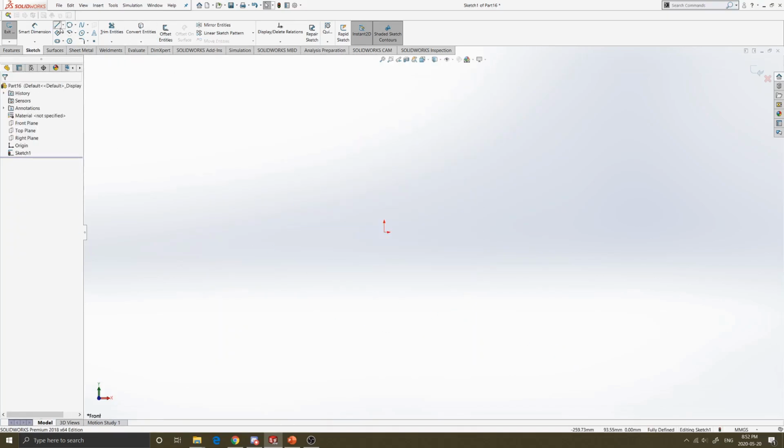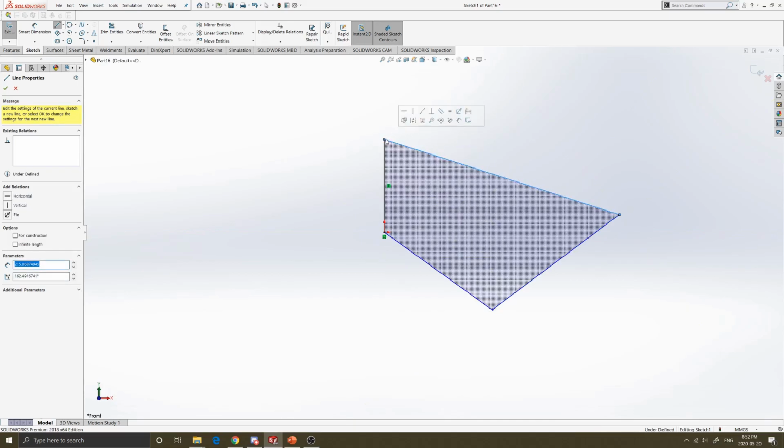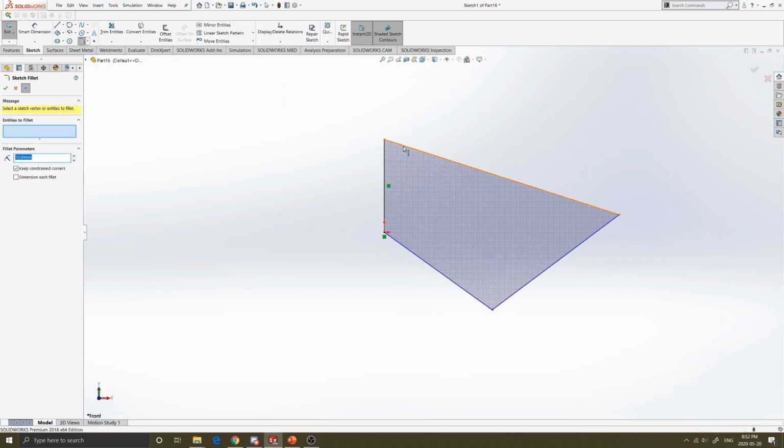Okay. And lastly, there's something called fillets, filleting lines. So basically, any corner between two lines of some sort, you can just basically add rounded edges. These rounded edges are actually pretty important when it comes to manufacturing, because most things when you manufacture in real life don't actually have sharp edges, like full 90-degree edges. And more often than not, you actually don't really want full 90-degree edges either, because those can be kind of dangerous and annoying. So yeah, important to include fillets in your final iterations.